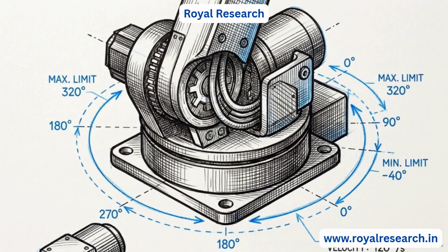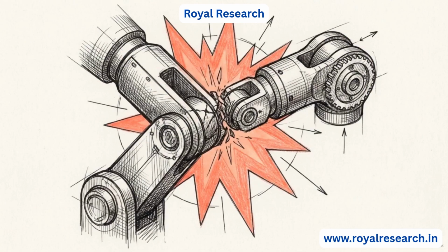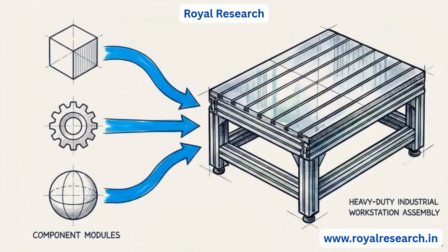We then establish frames. These are spatial reference points that tell the robot where objects are located within the room. To interact with the world, we add a tool, like a gripper, establishing a tool center point. Ensure you input its precise dimensions. If off, the software miscalculates clearances, causing undetected collisions. Defining these frames and tools accurately is the specific step that transforms a simple 3D model into a mathematically reliable simulation.